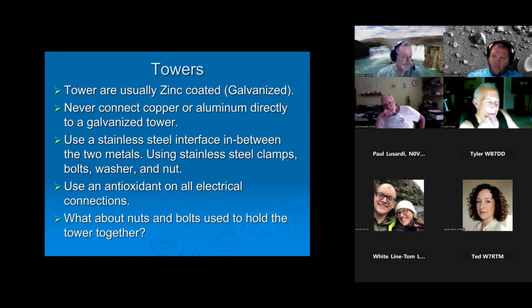And the thermite basically fuses copper. In other words, it burns copper into copper for a mechanical connection. Actually, it's all one piece of metal. So there isn't any way for oxidation to get in there because it's all fused together. Thermite basically goes off in a great big flash and burns for a bit, creates a whole lot of heat, and then deposits copper around on copper. So it fuses things together.